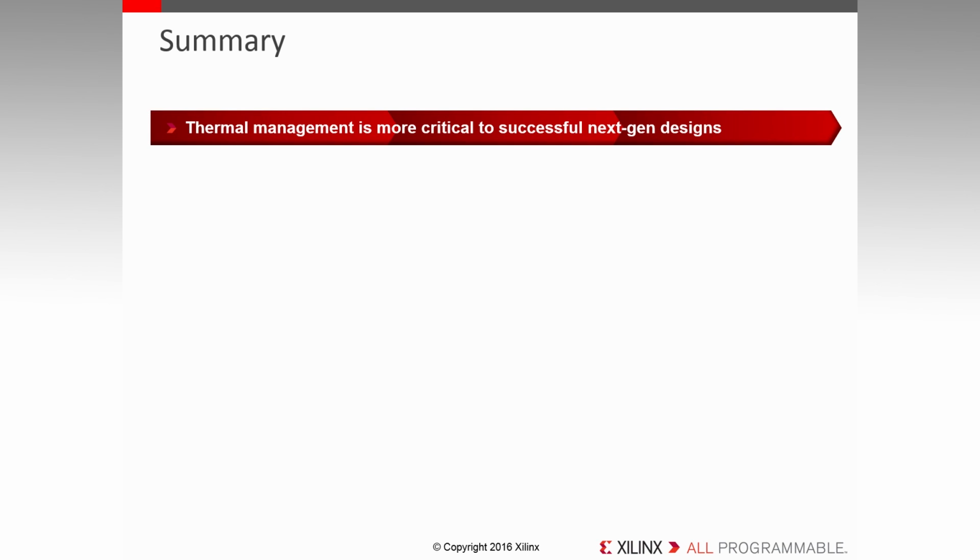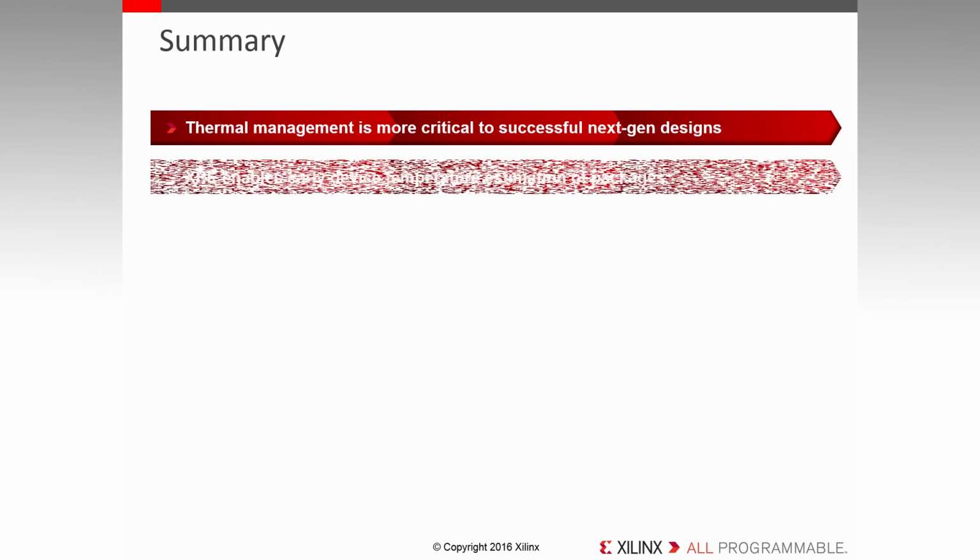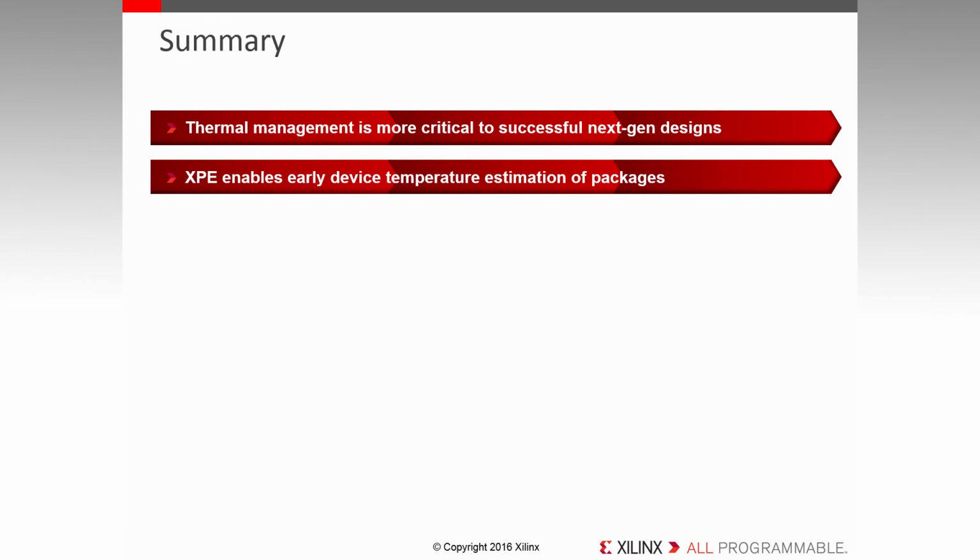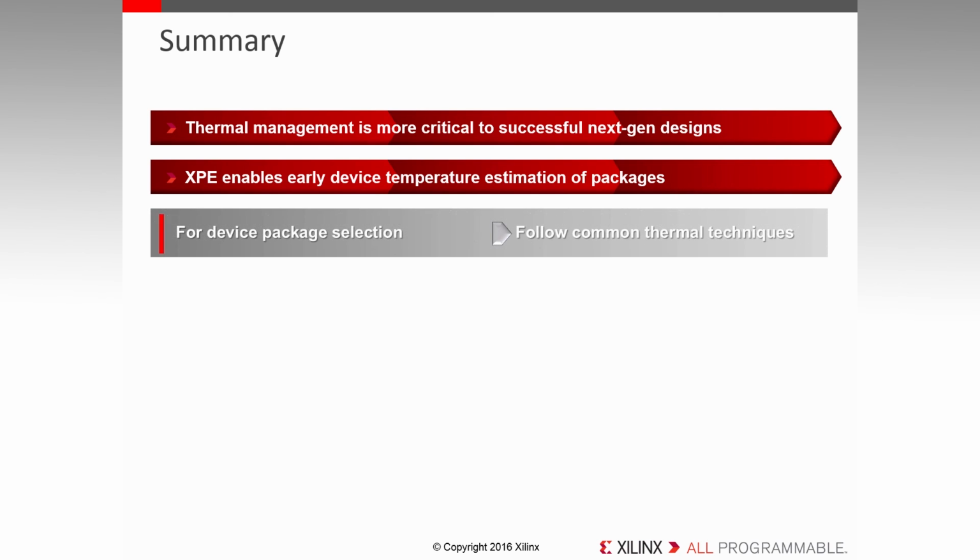In summary, thermal management is definitely crucial to successful next generation designs. System reliability, performance, power, cost, and life factors are determined by the operating temperature of the device. XPE enables early device temperature and power density estimation of packages and allows customers to better understand and track FPGA junction temperature throughout the design process.